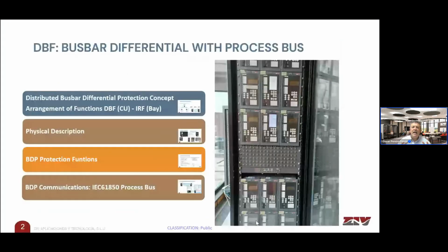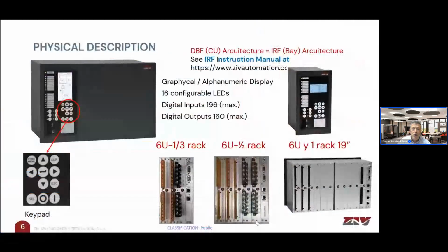Well, this is regarding the concept of our distributed busbar protection and how the different elements are interconnected. With regards to the physical description, you should know that both the central unit and the bay units share the same platform. It's our F family, based on a modular solution that is expandable, as you can see on the screen.